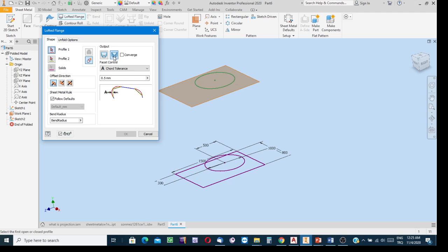After creating the loft, you're going to understand what I mean. First profile indication button is on, so indicate this to say that only the rectangle is the profile. Make a click along the edge of the rectangle. Do not indicate the circle. And then second profile button is on. Indicate the second profile, not here, of course, but at this level.